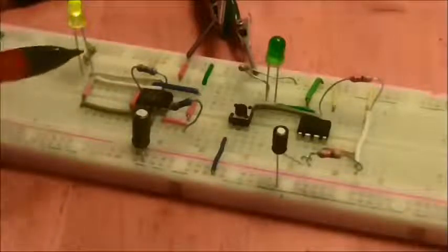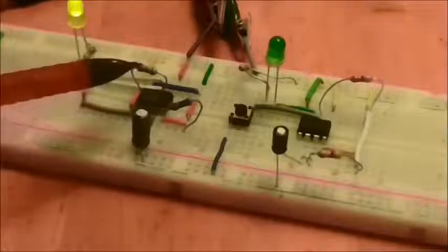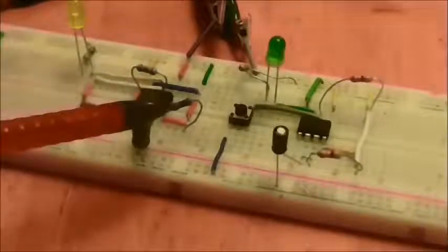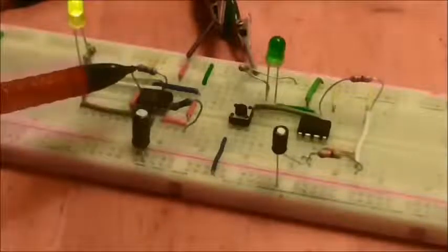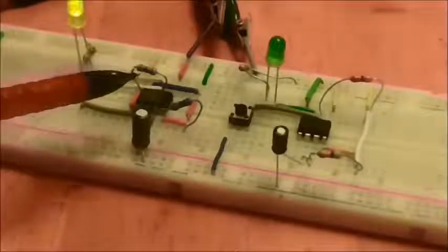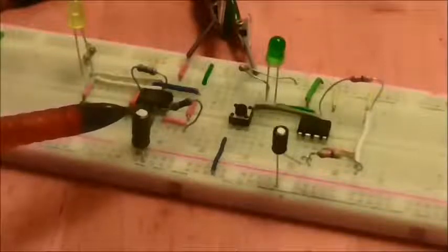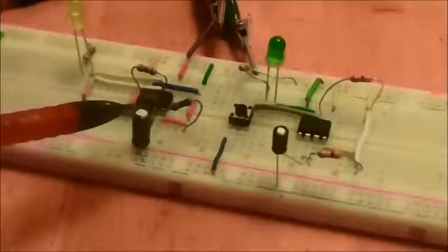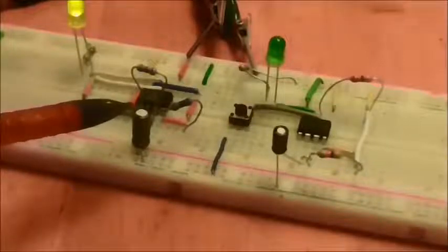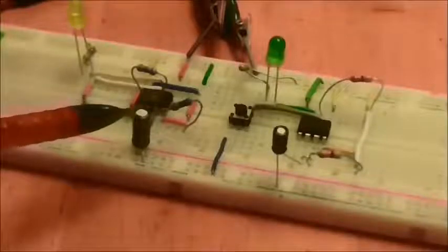And the first thing we've got to do, of course, is to add together R1 and R2. And as R1 is a 10k and R2 is 100k, that gives us 110,000. C1 is a 10 microfarad capacitor, but it's no good to us in microfarads, we need it in farads, and of course 10 microfarads is equal to 0.00001 farads.